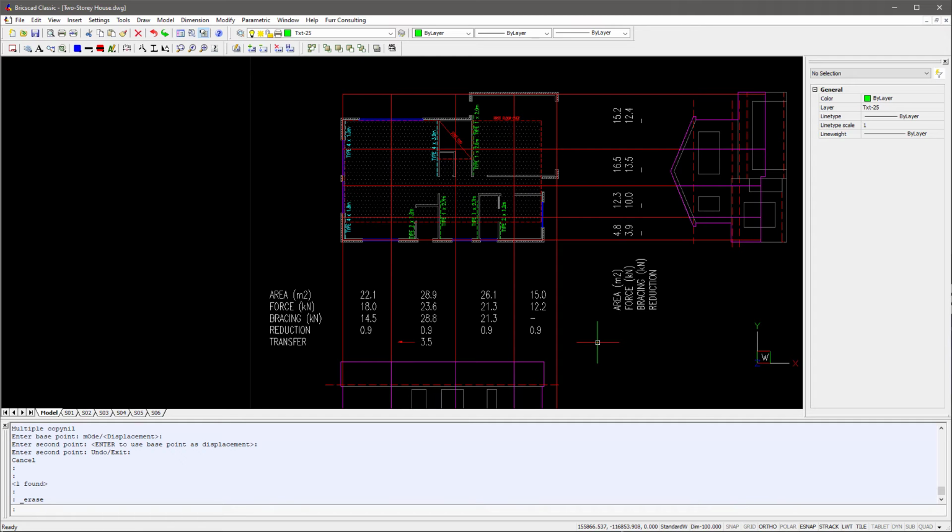While we're on this topic, something to also be aware of is any wall recesses or alcoves in rooms like bathrooms, which will also interfere with bracing. You also need to consider the placement of bracing on bathroom, laundry and kitchen walls, which require penetrations. Stair voids are another area to think about, as the floor level above may not be restrained and so will often not be an appropriate place for bracing.